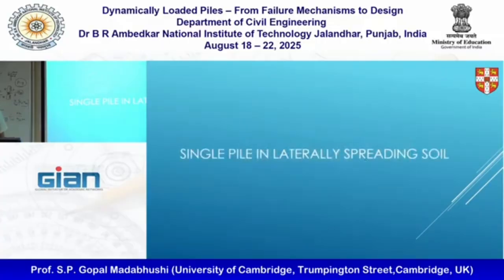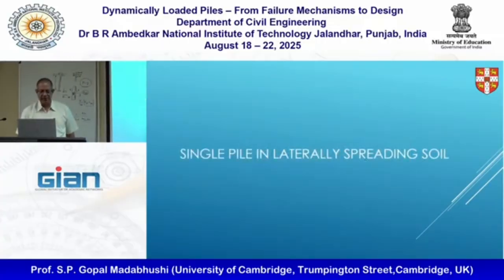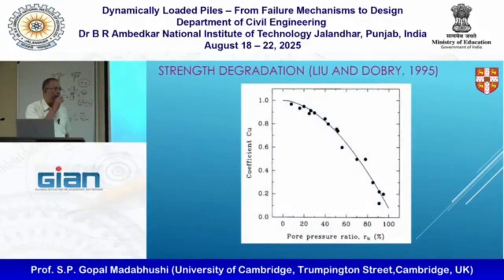So far, these are all the things we need to know about piles and laterally spreading soils, and how we can adapt the traditional p-y analysis to fit into those models, like Goh and O'Rourke or somebody like that. What I felt when we started this journey was that this is all based on cyclic triaxial tests and everything else, other than actually doing proper physical modeling.